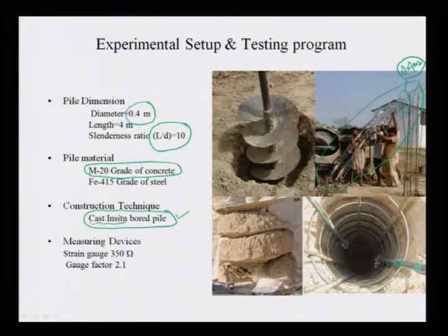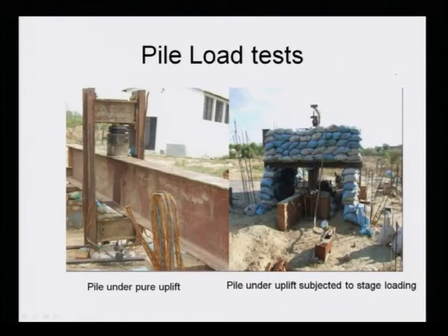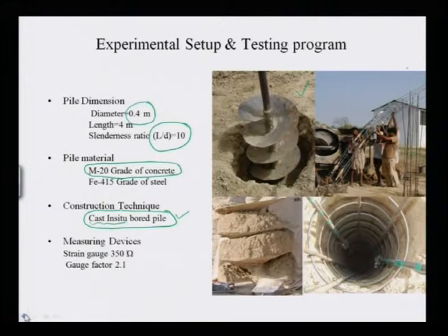The casting of the pile has been done in the site itself. If you look here, boring has been done in the site. After boring, the entire preparation and casting of the pile has been done in situ. That is why it is called a cast in situ bored pile.